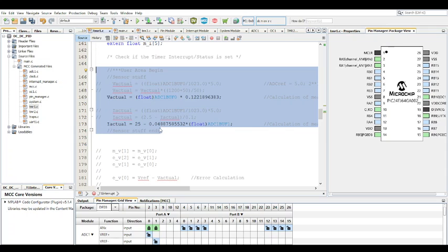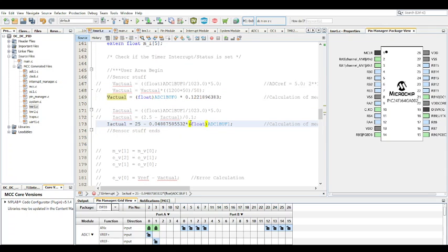There's the voltage sensor and the current sensor. You could also get a current shunt. Obviously you're going to have to figure out what the scaling issue is there and modify this part here if you have a current shunt. The main thing you have to modify here is this one, the gain. This part stays the same because you're literally just getting the voltage, and the next part you have to change is this part right here, for a different resistor voltage ratio. Remember, 1200 big resistor, 50 small resistor?